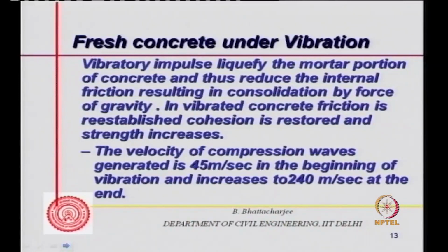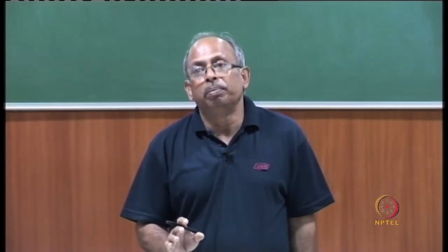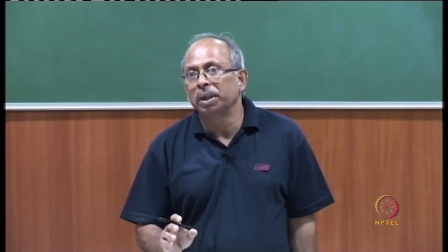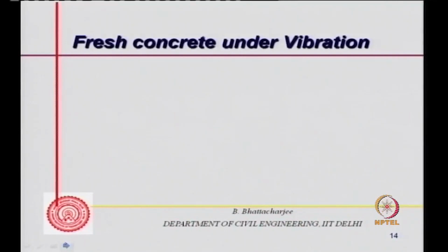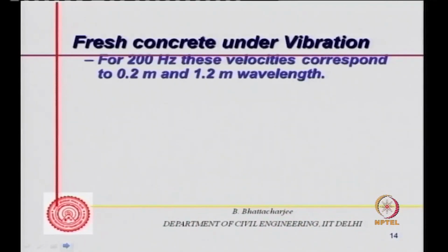That's because the water within the pore system would vibrate more or move more than the solid particles and cause an excess pressure in the system, and that reduces or overcomes the friction within the particulate system, and results in mobility or movement of the particles, and also drives out the air.